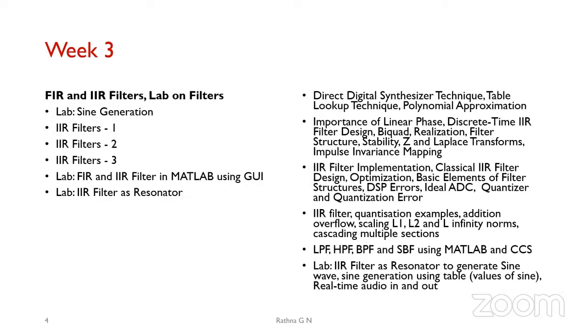The last stage is that I have to do digital to analog conversion. So there also the DAC will be giving error, basically because it is approximately mapping. So considering all this, depending on the application, you have to see what kind of filter, what kind of hardware, and how many bits you need. Whether you can mostly use these basic boards for your own application: for most audio and speech processing, it is enough to have 16-bit processors.